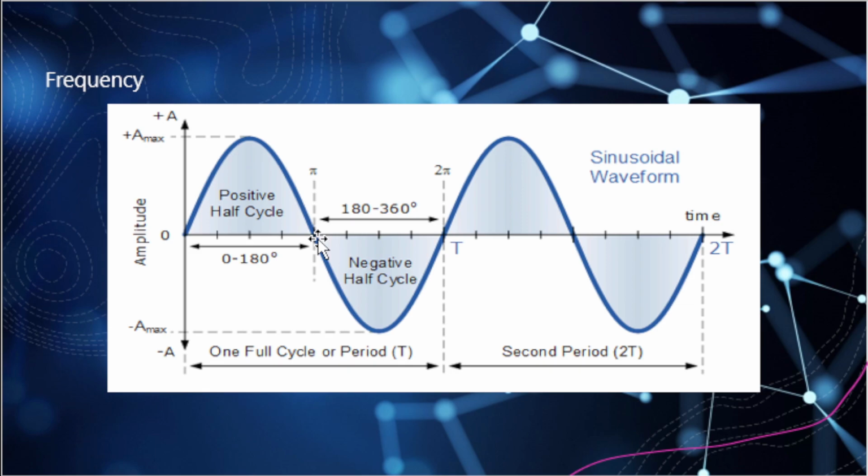And then, the last part of that accuracy that we mentioned: if my measurement device is only accurate up to 1 kHz, and my signal is 1 kHz, then it's possible that what I'm seeing displayed on my oscilloscope could look more akin to 2 kHz.